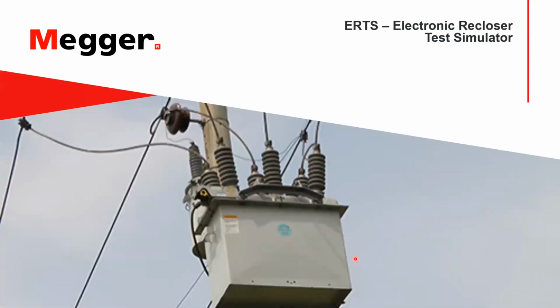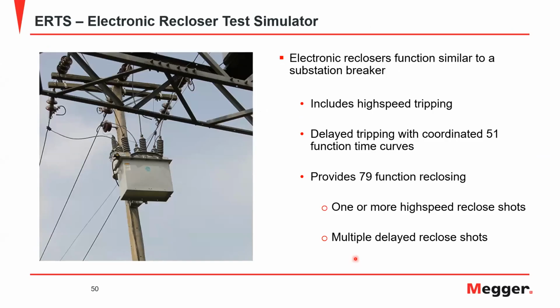Okay, so now we're going to jump into electronic recloser testing. In general, reclosers, with regard to reclosing, are very similar to a breaker. Both a recloser on a pole or in a switchgear and a breaker in a substation provide multi-layers of high-speed tripping, time-delayed tripping, high-speed reclosing, delayed reclosing. They function very similar with regard to their basic trip and reclose functions. So how do you test them?